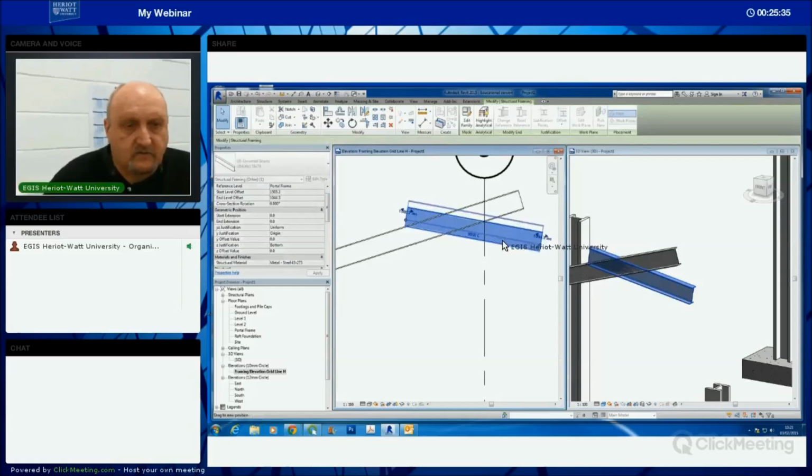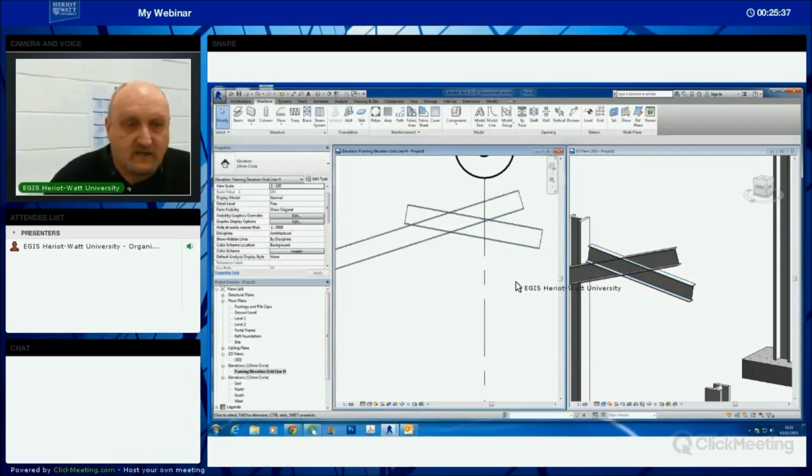And tidy that up just a smidge. So this is the bit of that beam there that's going to be the haunch, the central haunch, and I'm going to trim it as well. Now, to trim it, we use the reference planes, and I don't want this reference plane to be on this grid line because I want to make a gap here. So we're going to have a space between the end of this original beam, the haunch beam of, I'm going to make it 25mm.